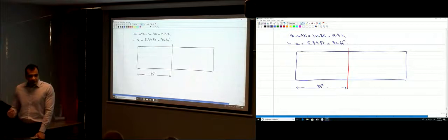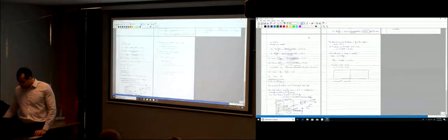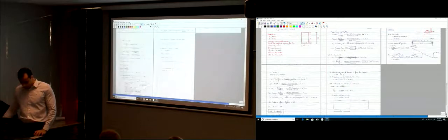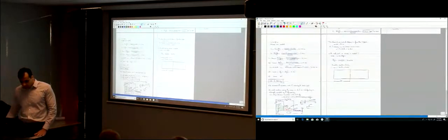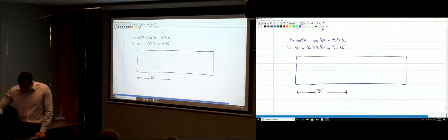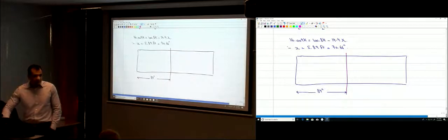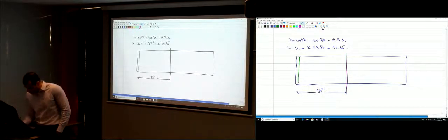And then we're going to start providing stirrups. Okay? How will we provide stirrups? Let's use the same colors that we had here. Okay, green, we use green. So let's see here, page what? Green, red, and then purple. That's the purple. Yes. So green. So I'm going to provide stirrups at a spacing of 5 inches. Where would I provide the first stirrup? As a practice, we're going to go 2 inches from the face of the support here. So the first one is at 2 inches.